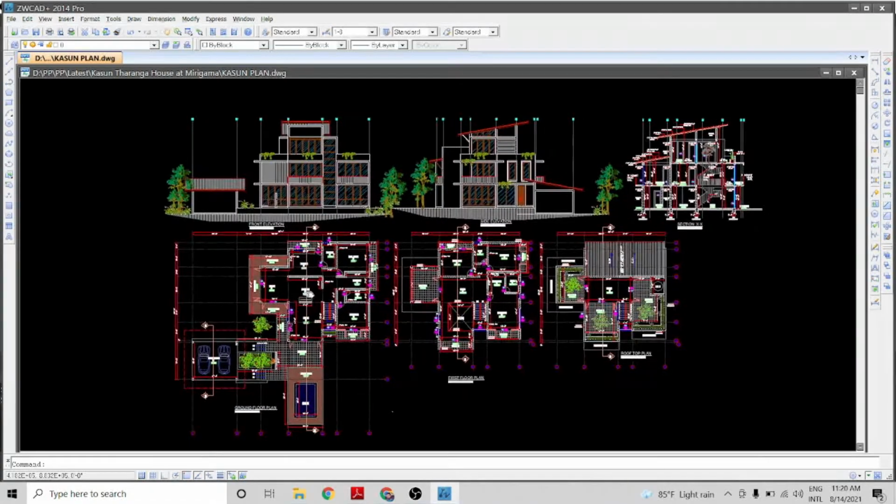The first most important thing is to develop the best structural form suitable for the structure. The structural form is where you are going to put the structural columns and beams, how you drop the slab, and what the levels are. That formation should be developed at the earliest stage. You should not make any mistake in the structural form, otherwise you will suffer economically as well as from construction and architectural points of view. You will face a lot of problems if you don't go for a suitable structural form. The most important thing is to prepare the structural form.